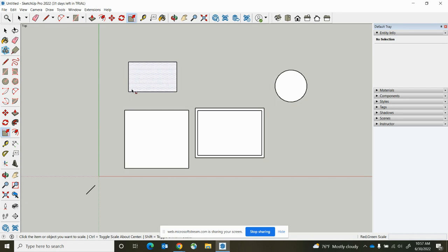So with this, let me double click this, hit my scale button. So I have it here. And now I can either do a uniform scale to it, and at the bottom it's telling me what that scale is, or I can just come down and type. So maybe I want my scale to be 1.5 times what it is. Oh, it's not gonna let me do that. Hold on a second. Oh, okay.